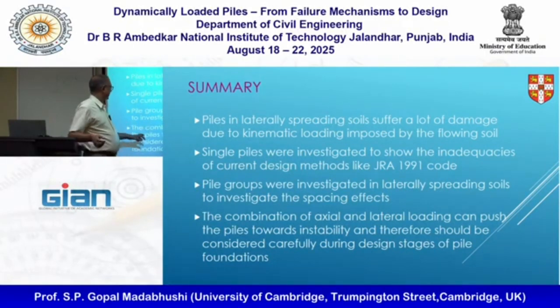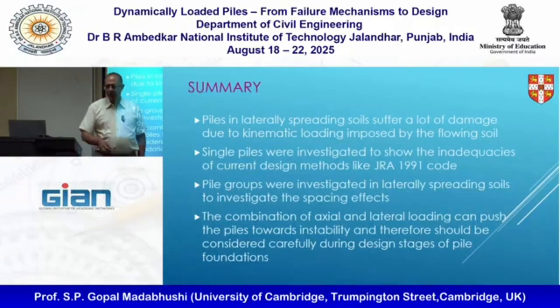So you need to consider the combination of axial and lateral load, and that can push the piles either towards instability in one case, or if you design them more carefully, towards stable yielding. And obviously my design recommendation will be, try and design your piles to suffer stable yielding. That is always a safe design. Unstable collapse never is. Okay? Right.